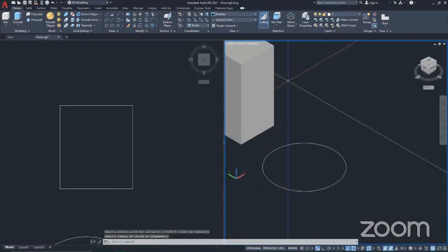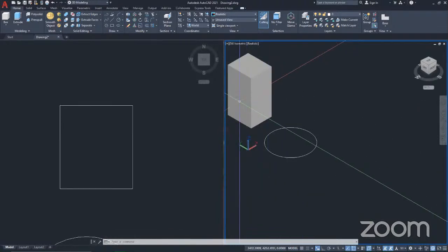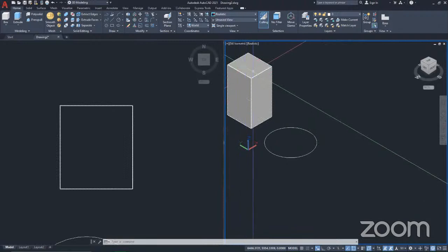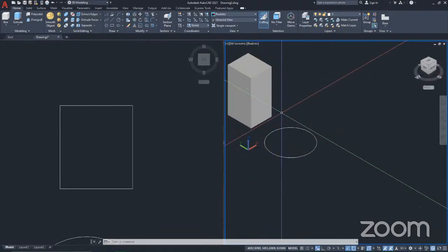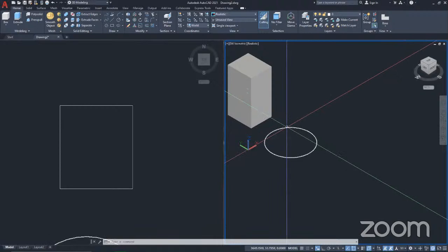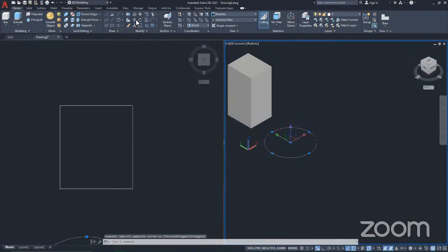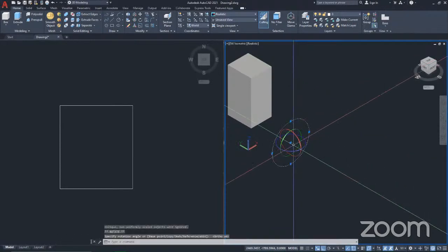What if I want to create this circle on this face? What if I want to create it on this other face or on this part here? Okay, this one is also the XY plane. What if I want to create it here on the ZX plane? If I want to create something here, there are ways to go about this. Now, this one is a little bit difficult. You have to use some other tools, like 3D Rotate, to rotate it to fit your axis. So if I turn on my orthogonal restriction and keep it like so, then I can move this and place it somewhere here,